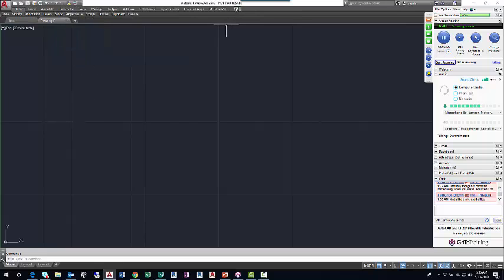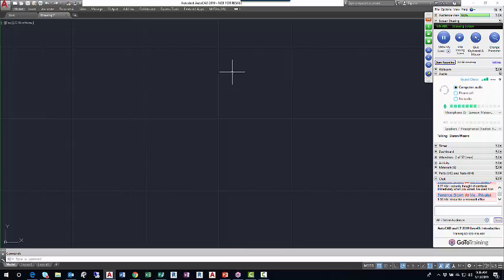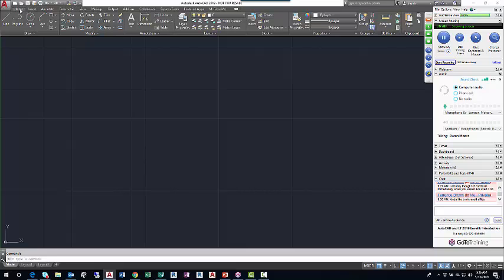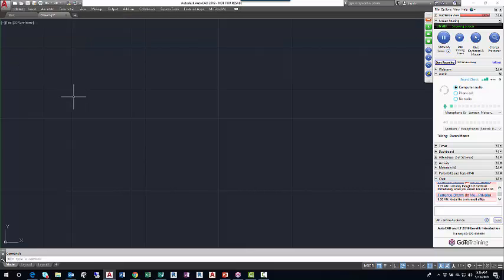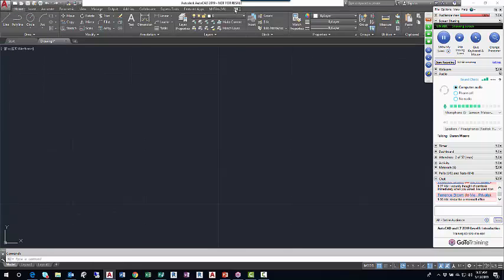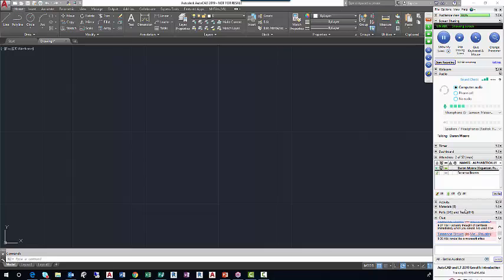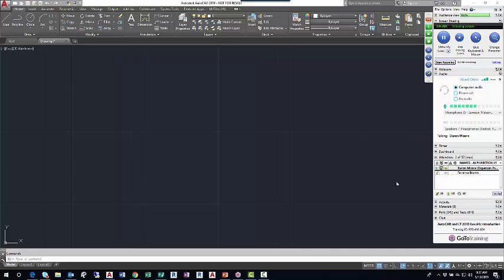Third left click minimizes me down to a single title per tab, and if I left click on the Home tab, it expands and shows me the tools. Now I can left click my command, and when I move away from the ribbon, it will fold up and get out of my way. So there's the final click, that fourth click, which just restores us back to full display mode. And this is a nice display mode for a larger monitor or what have you.